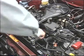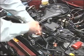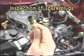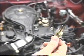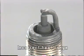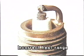Now let's take a brief look at inspection and adjustment methods for the IIA ignition system. You can tell the engine condition from the color and condition of the spark plug's electrodes. A light brown color like this shows that the engine is in good shape. If the electrodes are black like this, the air-fuel mixture may be too rich or the spark plug heat range may be too high. If the electrodes are white, the air-fuel mixture may be too lean or the electrode heat range may be too low, causing the electrodes to scorch.